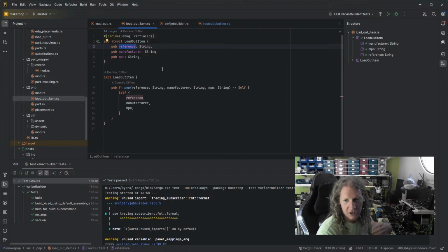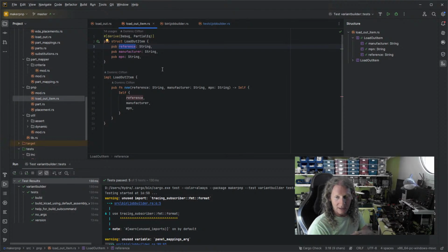And a machine can have a loadout, which is fine. And when you're manually placing stuff, if you printed out your loadout, it will be the list of components that you need to look for in all your parts. Pull those bags out and put them on the desk next to you so that you can take them out when you need them, right?